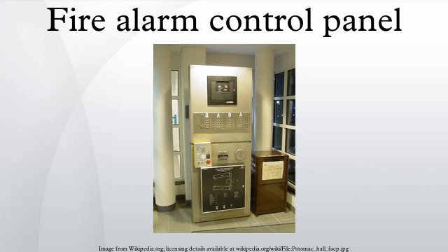These annunciators may employ a graphical representation of the zone boundaries on a floor plan using textual descriptions, illuminated icons, illuminated sections, or illuminated points on the map corresponding to initiating circuits connected to the fire alarm control panel. For this reason, slang often inaccurately refers to initiating circuits of a fire alarm control panel as zones.